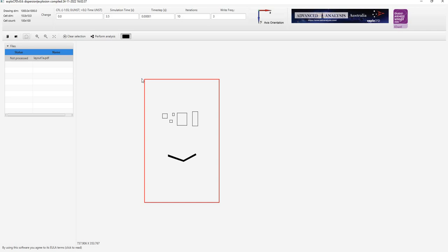The other thing is the PDF generally has boundaries along this red rectangle, and underneath the red rectangle there are lines that you could see clearly here. If these lines are not excluded, they'll be treated like walls, and that's not what we want, because if they're walls, you're going to get shock waves reflected off of them. It's as if you're doing an explosion in a massive room. So we excluded everything, and then we went back and included what's on the inside.